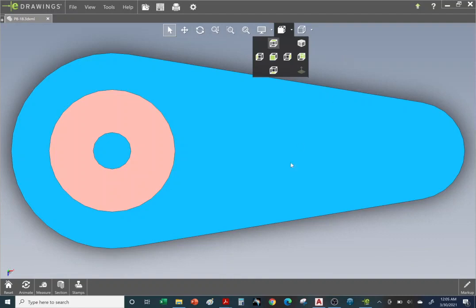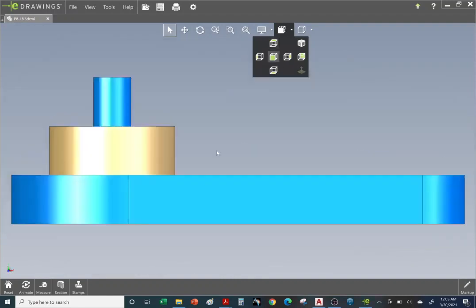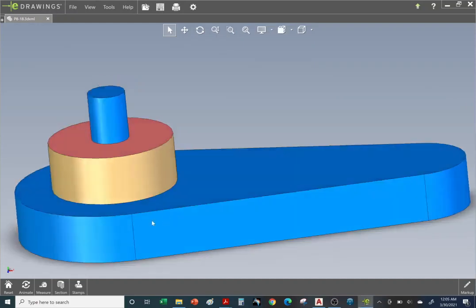All right, so let's take a look at the front view. And by the way, you don't draw the tangent lines, right? This is where we go from a flat surface to a cylindrical surface. We ignore the seam, right? Because you actually don't see it. It's a nice smooth transition. Same thing with this one, and on the opposite sides.